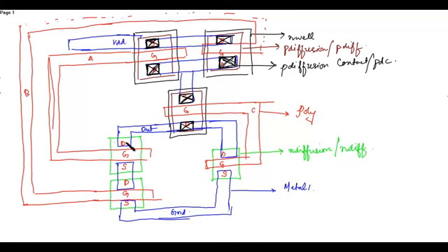Similarly, we have to place the N diffusion contact, since we have to connect the metal layer with the N diffusion layer. So this is the N diffusion contact. Okay. Similarly over here, wherever there is connection between the metal layer and the N diffusion layer, there we have to place the N diffusion contact.